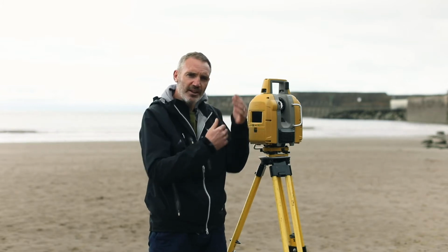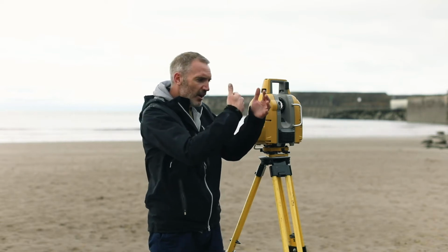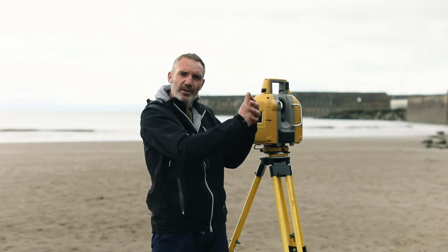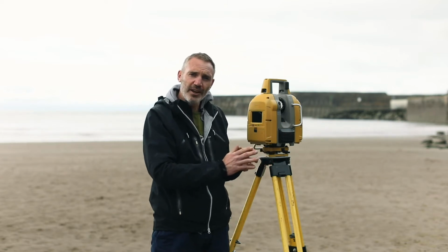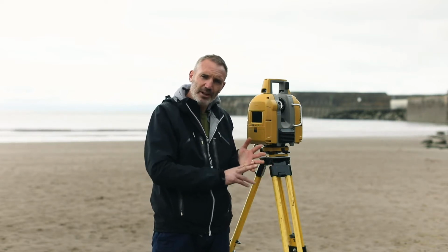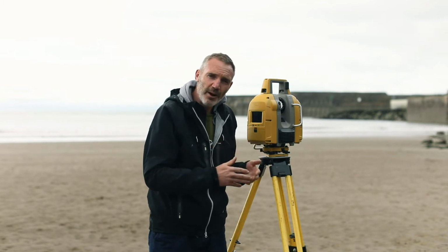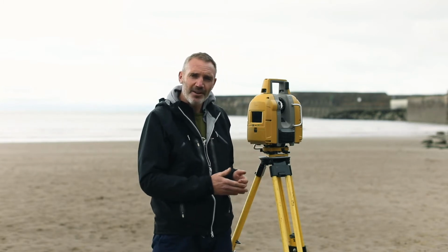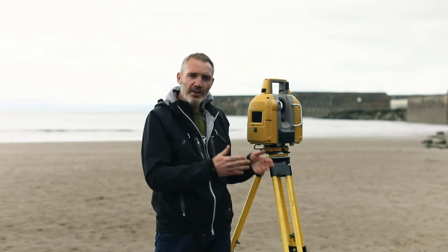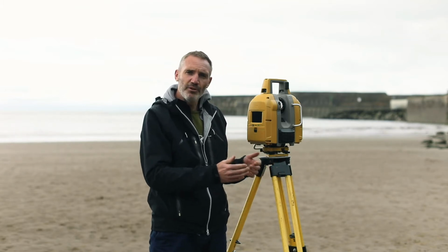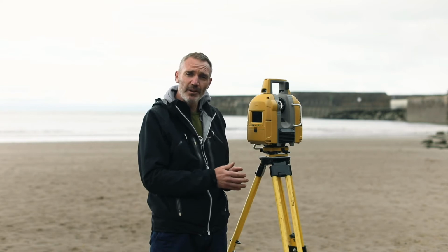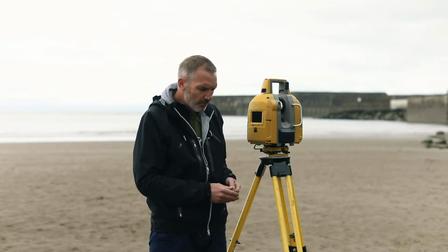So it's shape fitting, taking the shape from one scan and another, fixing them together, and retrospectively solving the position of the scanner. That's cloud-to-cloud registration, and it works really well. It's pretty much one click of a button in the software, but it's dependent on having good overlap between the scans. Typically we want to think 20–30% overlap is good enough.